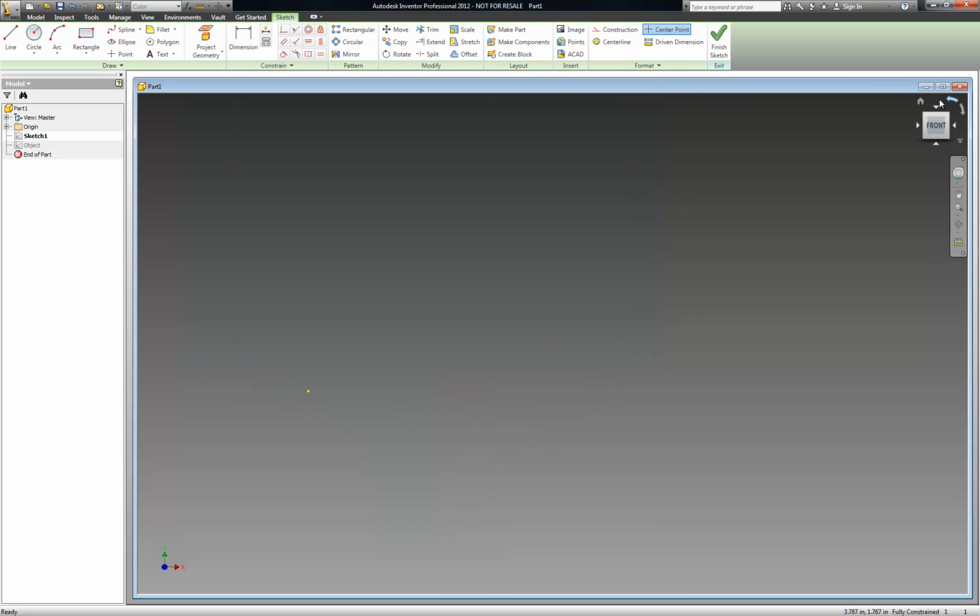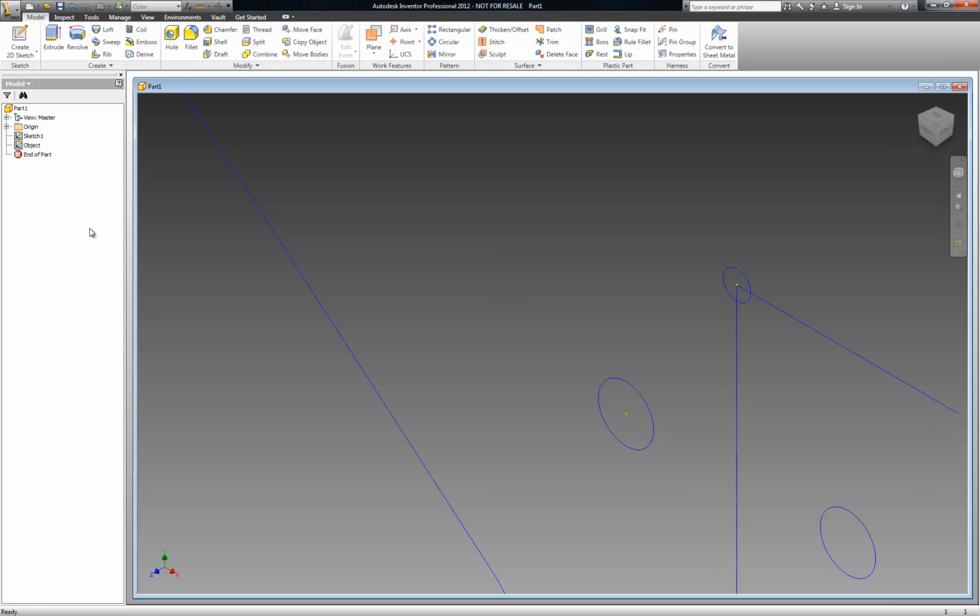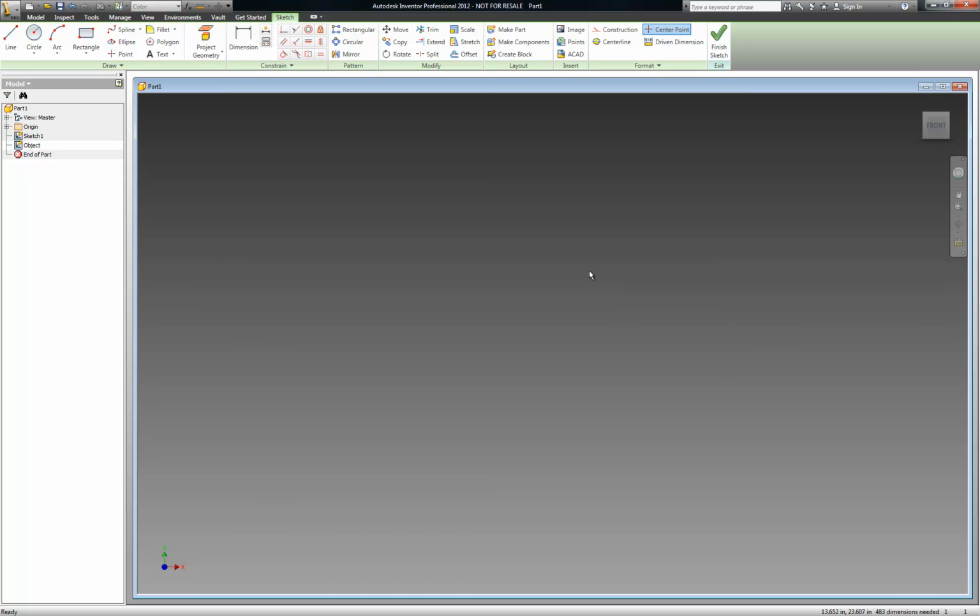Okay. And I guess we're finished 2D sketch, and object is what we want to edit. Edit sketch in the object. There we go. So we're editing the object, not the sketch. Okay, we're going to go in here. Now we've got a little circle here that I used when I was laying everything out. I can delete that. Delete these lines here.